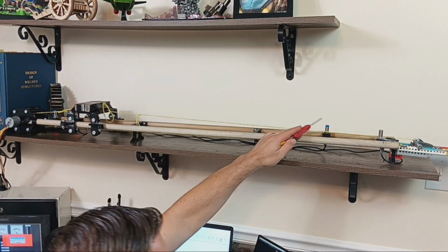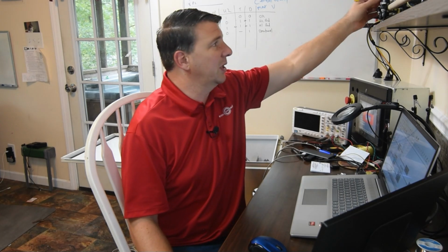So at this point, it does what I want it to do, and it gives me an error and says, hey, something's wrong here. Now, it may have just been a fluke. It may have been going too fast. It didn't catch it. So what it's going to do when I clear this is it's going to look for that switch, the high prox one. Or it's got a timer on it. If that timer gets active, then it will say, hey, something's not right here, and we're going to kind of shut down. So if it hits this one, though, it's going to send itself back home. It says, I got the signal I wanted. Boom. So I'm going to go ahead and do that. And now it's going to go back and rehome itself and get ready for launch.